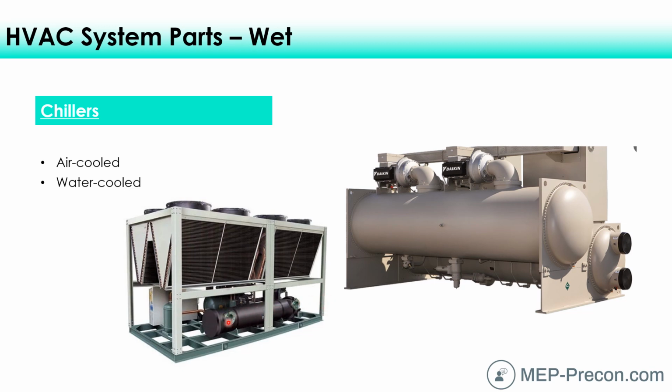So we're going to have a pump here, and it's going to pump chilled water. Don't worry about where we get that chilled water for right now, but we're going to have chilled water flowing through these fan coils. Remember the coil that we have? We're going to have these fan coils in different zones within the building, and those are going to absorb heat within the space. And as they absorb the heat, that water is going to get warmer. It's going to get returned here.